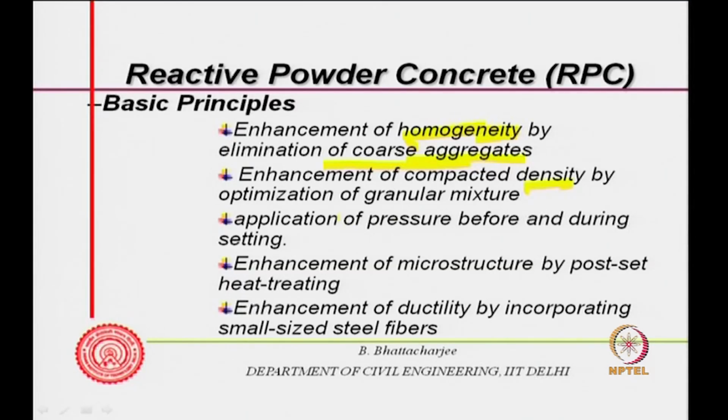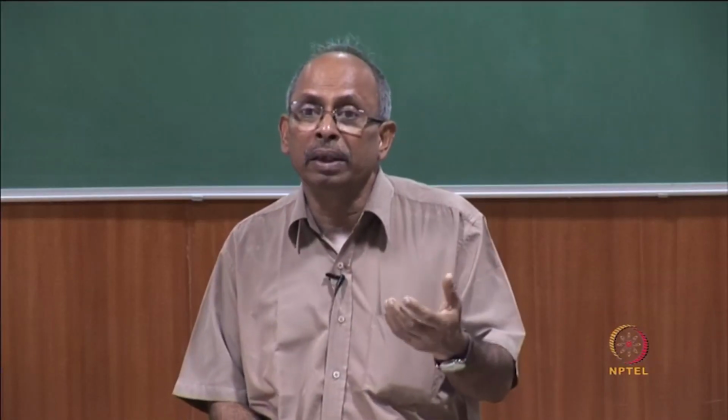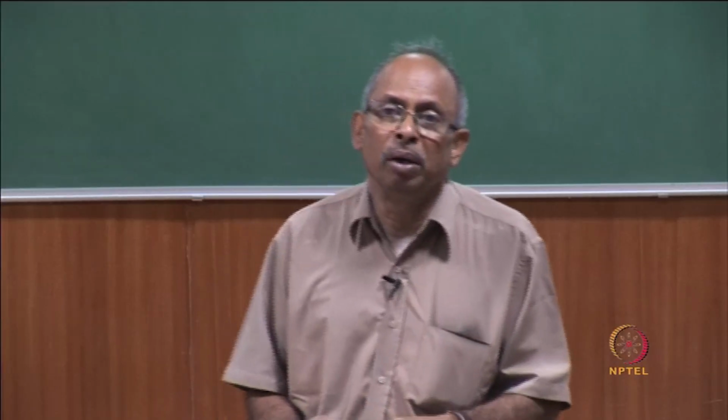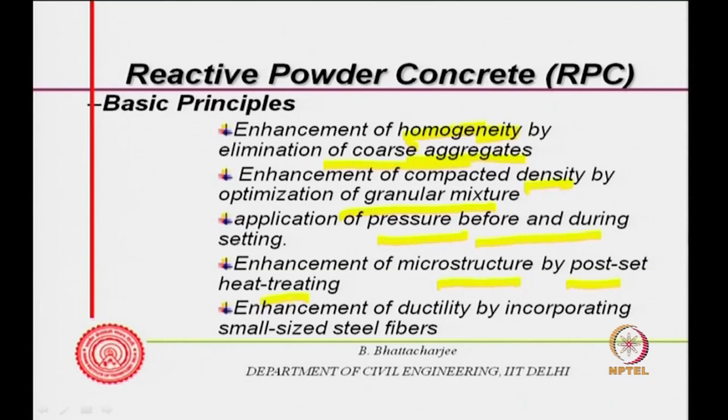The compacted density by optimization of granular mixture. So, you have to do a thorough packing density scenario, apply, but this is additional, apply pressure before and during setting. Now, this would ensure further compaction, and if you are going to a very high strength situation, this would be a requirement. Microstructure enhancement by post set heat treatment.